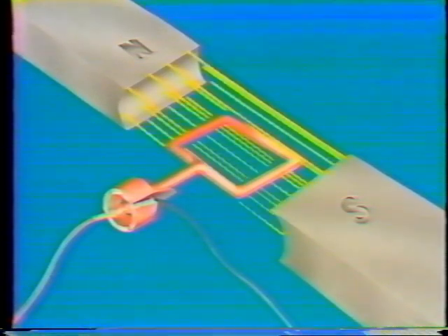This DC generator operates like the simple AC generator too. As the loop rotates, it cuts through the flux lines of the magnetic field. This action induces an AC voltage in the loop. The voltage remains an AC voltage until it reaches the commutator. Then, the AC voltage is converted to DC by the commutator. Knowing exactly how the commutator is built and how it interacts with the brushes is the key to understanding how this generator works. So let's look at the commutator and the brushes a little more closely.